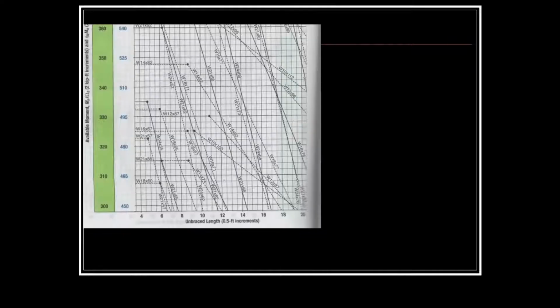With green values for ASD and blue values for LRFD, we can pick out the LTB curve for any shape, show its plastic, inelastic, and elastic ranges as they continue from page to page within the book. So if you piece together multiple pages, you can follow the strength of a particular shape as it decreases with increasing unbraced length. So in red and black, here are the two shapes that I had previously graphed.